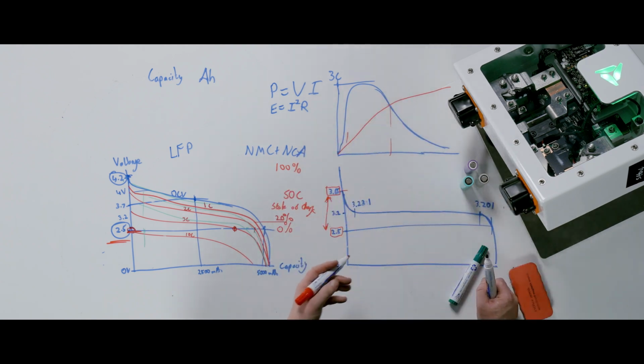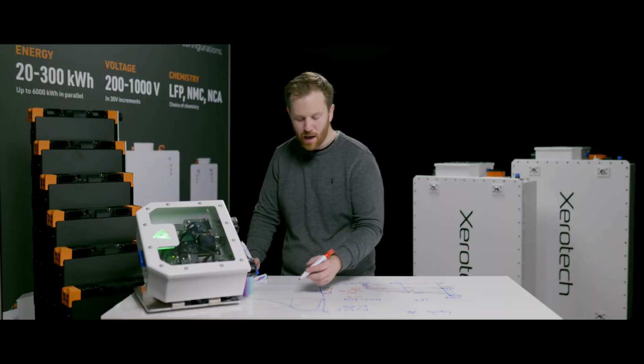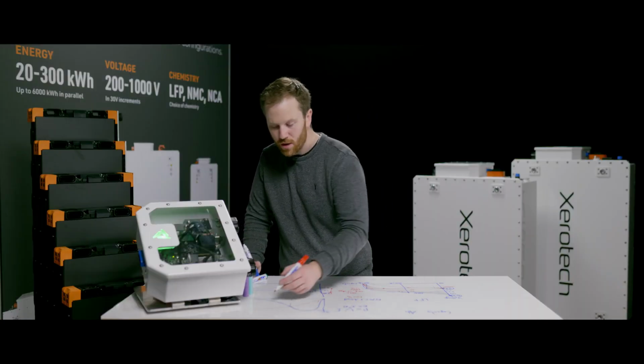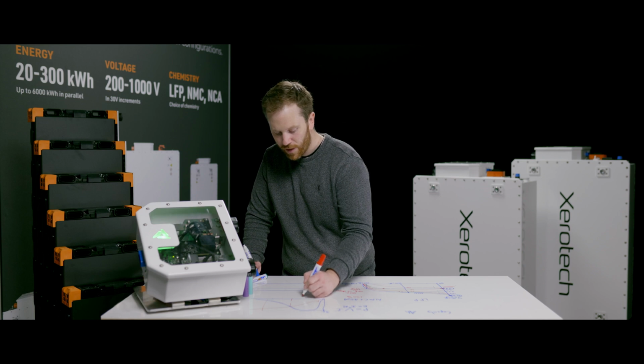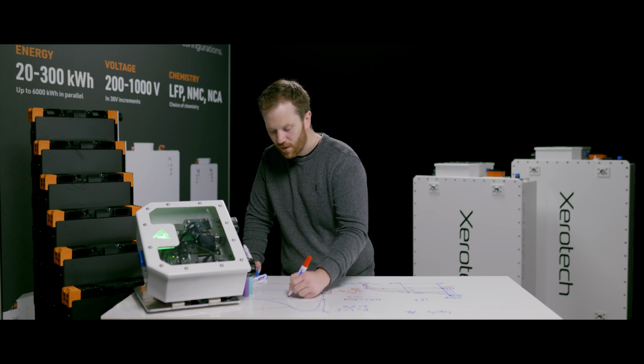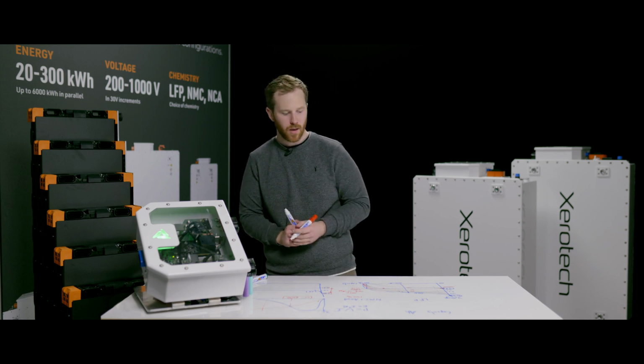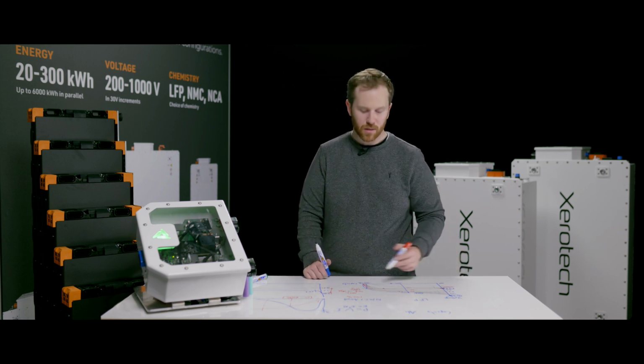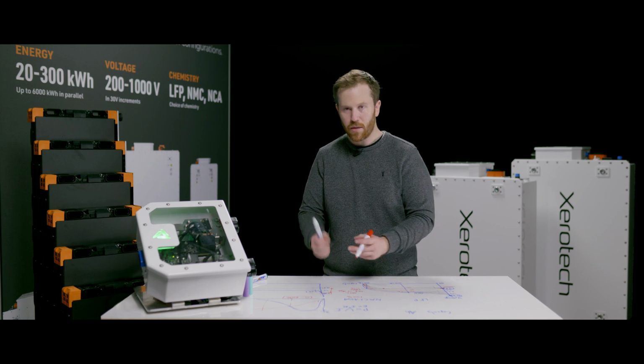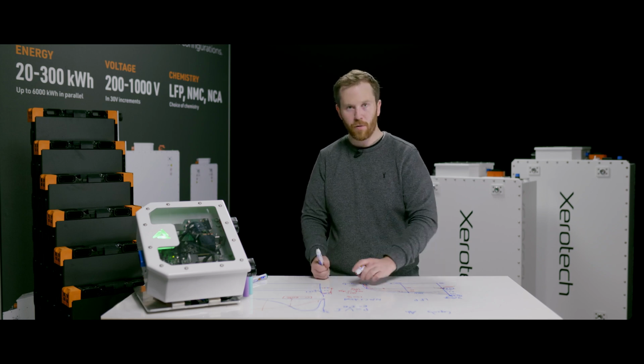So that's important for batteries and how you use them, because you'll be able to fast charge a battery usually from about 0 to 80% in a very short period of time. It could be 20 minutes, could be 30 minutes, because of these characteristics of battery cells: the internal resistance, the terminal voltage of the battery, and staying below the fundamental limits mean that you can accept much higher currents.